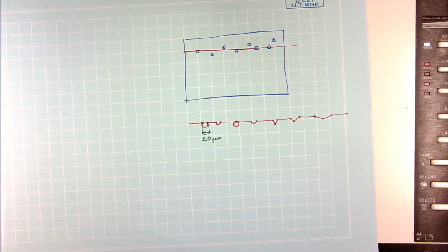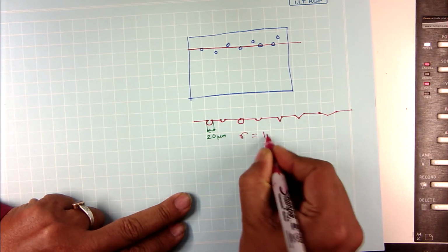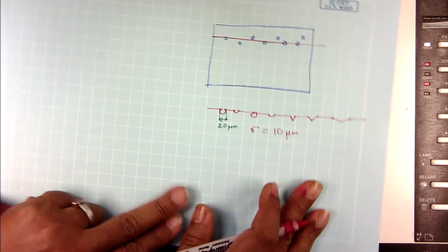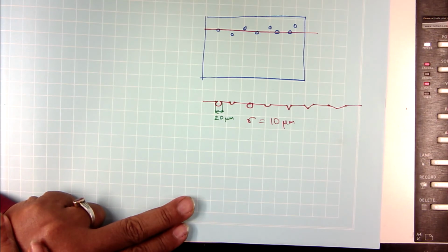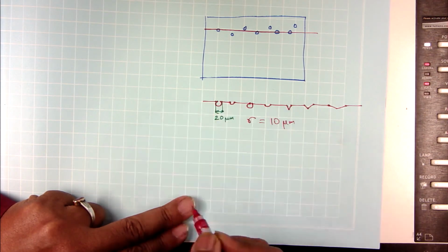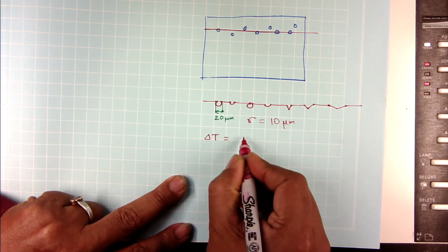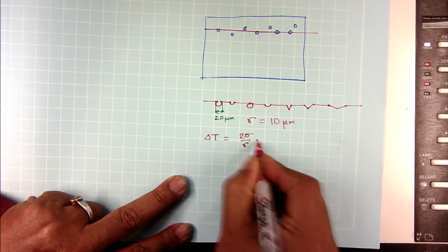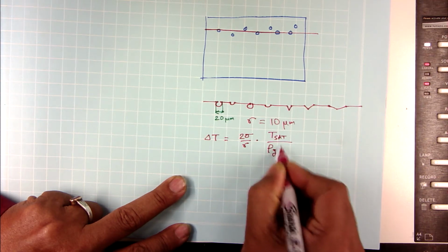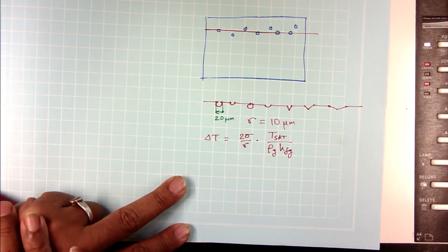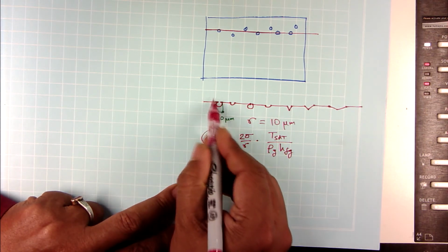Okay, which means the radius of the cavity R is equal to 10 micrometer. Okay. So, in order for this cavity to nucleate a bubble, if I go back and use it in this equation, delta T is equal to 2 sigma by R, okay. What is the value of delta T I will need so that a vapor bubble will nucleate over here?